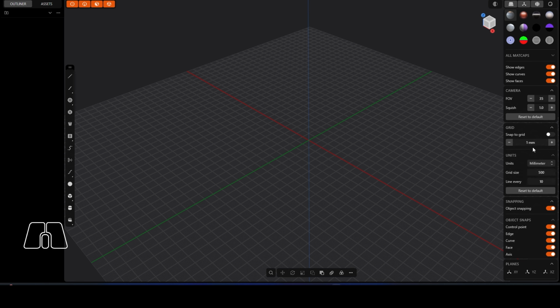I'm going to go for some sort of tabletop miniature here. So what we'll do is we'll drag out a center circle. So what's the shortcut for that? Shift C is the shortcut for that. Can drag that out. Good tip, you can use the tab key here. So we can go for a base amount of 160 mils.